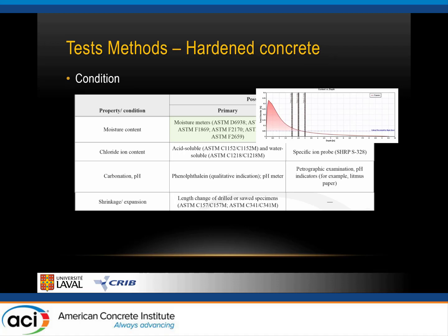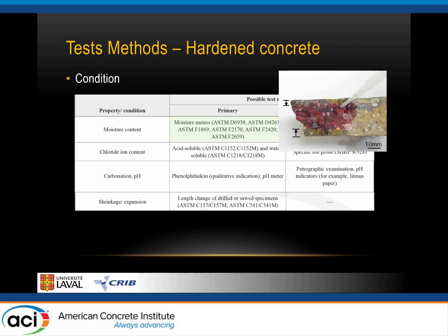some samples of cement paste in the concrete at different depth, and it allows us to evaluate the actual contamination of the concrete in different areas, and to evaluate eventually the vulnerability to corrosion afterwards. We can also evaluate the actual carbonation at different depth inside the concrete cover, and to evaluate further the susceptibility to corrosion initiation or eventually development in the first few layers of reinforcement close to the surface.